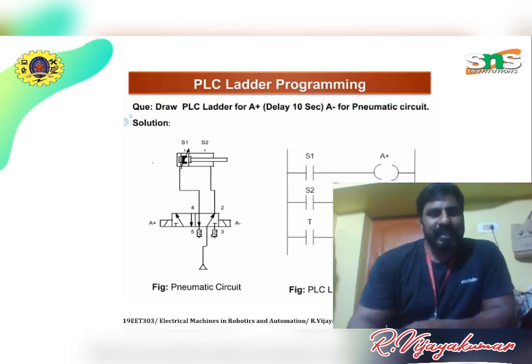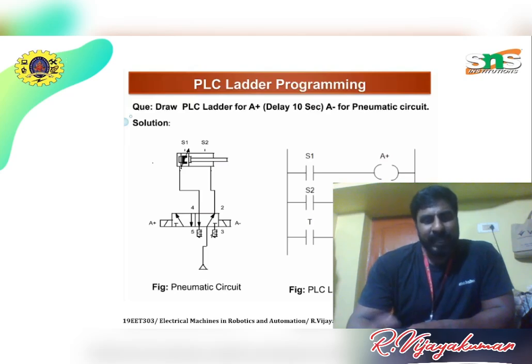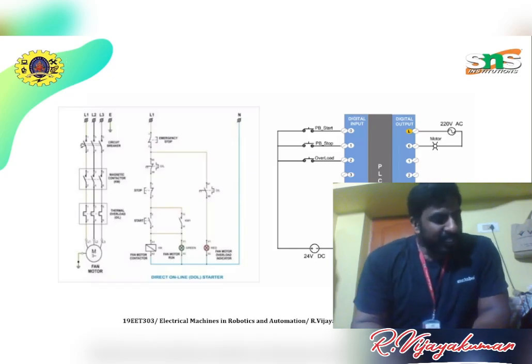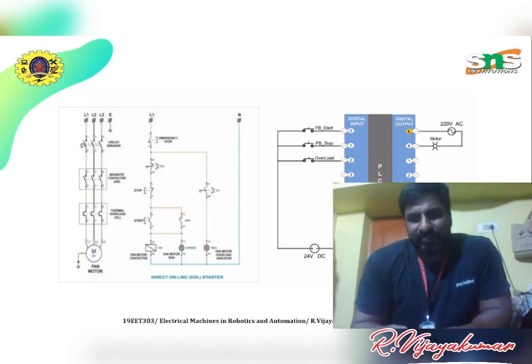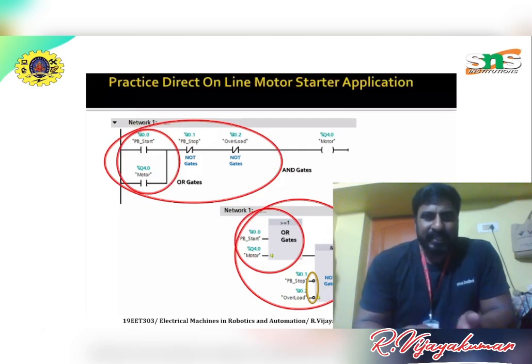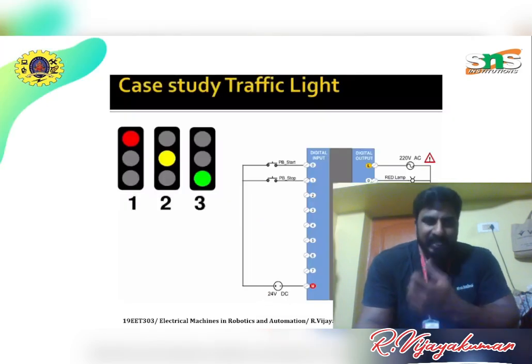In PLC ladder programming, we can take a pneumatic circuit. A pneumatic circuit is somewhat complicated, but it can be designed simply with the help of PLC ladders. Also PLC ladders are used, for example, for direct online (DOL) starters. We also make block diagrams, and with the help of block diagrams we can derive the systems. In a direct online motor starter application, we use a start push button and the motor.